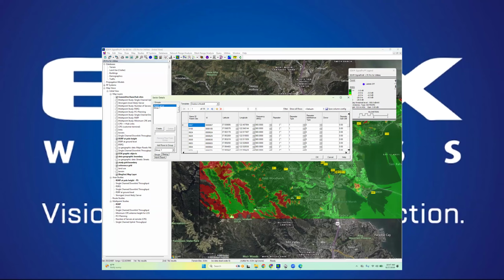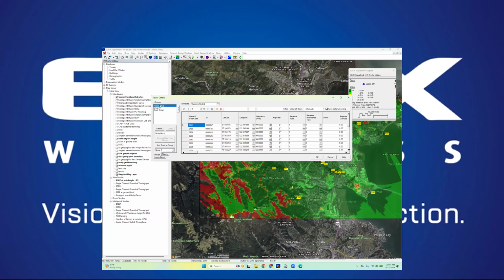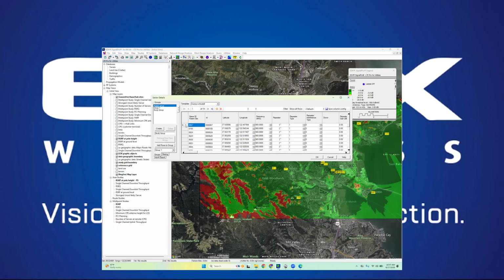I can create a group here. I'm going to call it study group and then hit create. And now this creates a subgroup of radios or base station radios in the project. If I highlight my master group, it's always going to show everything in the project. If I highlight the study group, well, there's nothing in here, so nobody gets shown yet. So what I'll do is, let's say, just by crazy coincidence, I only want to look at these first three sites and run their prediction.